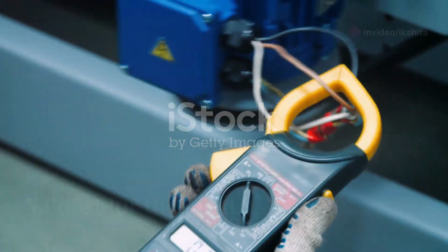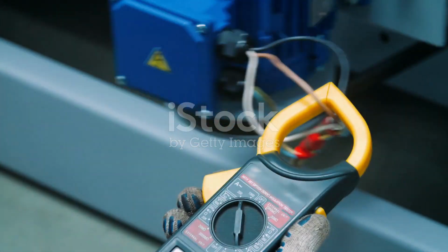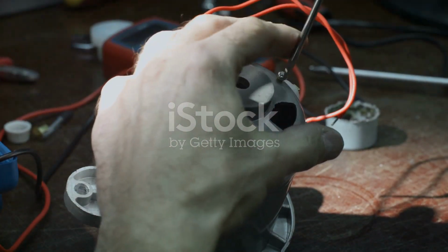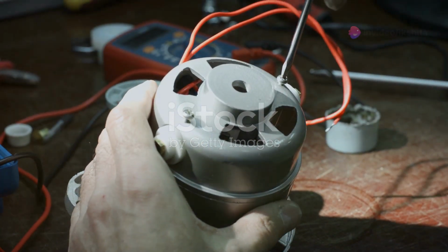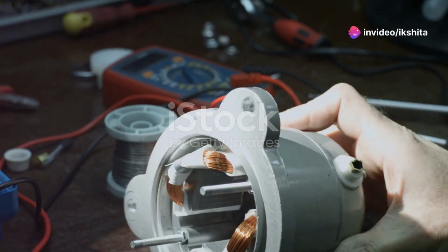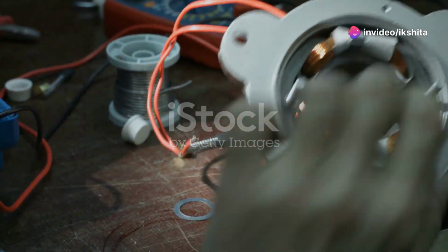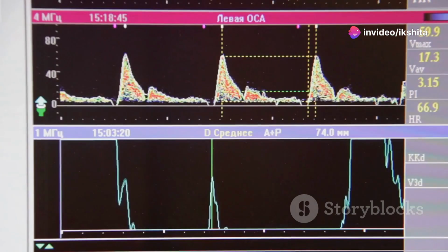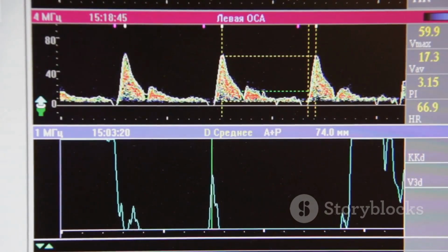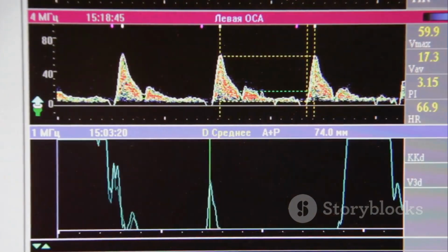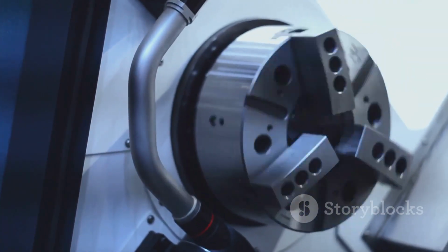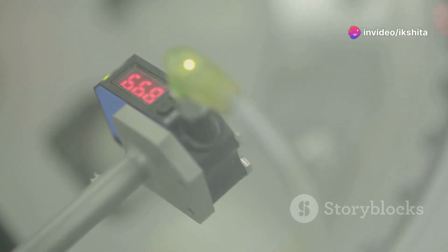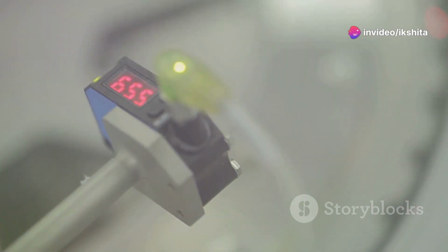The power factor tells us how efficiently electricity is being used. A lagging power factor occurs when the current lags behind the voltage, often seen in inductive loads like motors and transformers. In this scenario, the armature reaction actually strengthens the main magnetic field. It's like giving the rotor's magnetic field a little boost. This might seem like a good thing, but it can lead to increased iron losses and heating within the machine.